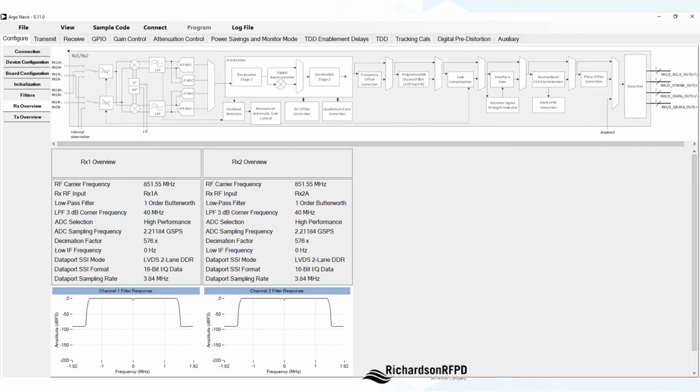The transceiver evaluation software, or TESS, is provided by Analog Devices and was critical for ensuring correct configuration of the ADRV9002. For the P25 demo, a custom receive configuration was generated using TESS. TESS was used to generate the sample code for configuration of the ADRV9002. This code was compiled as part of the custom baseband processor application that streamed the IQ data to the PC.